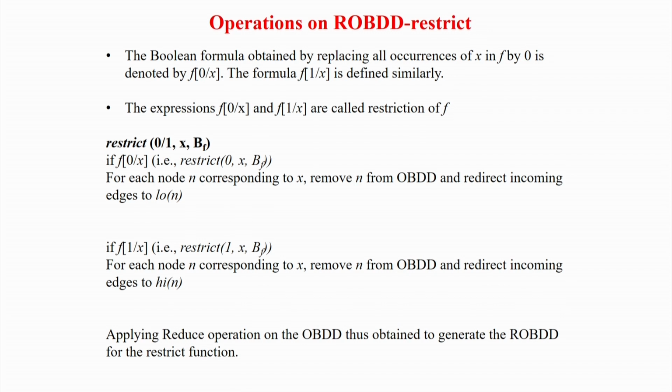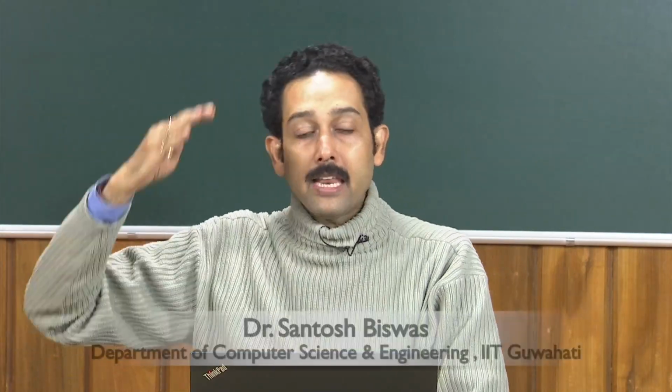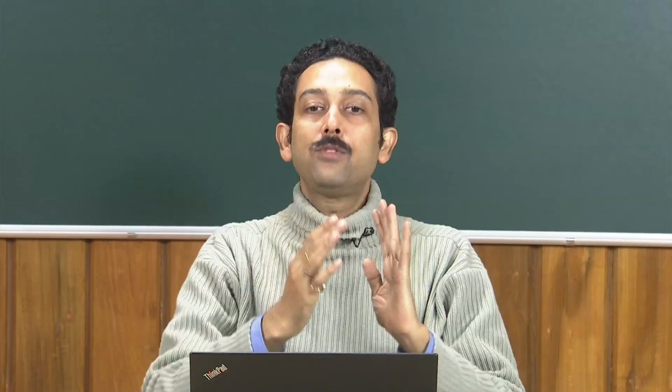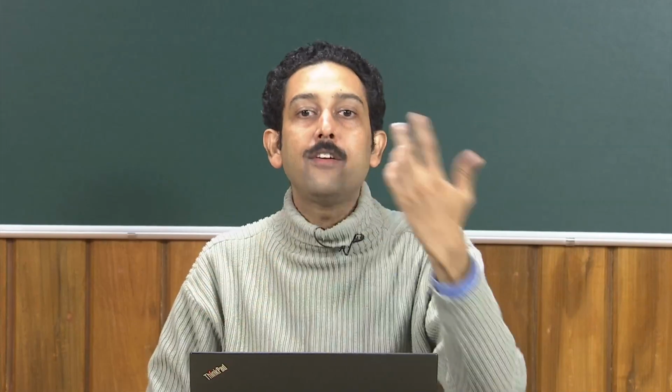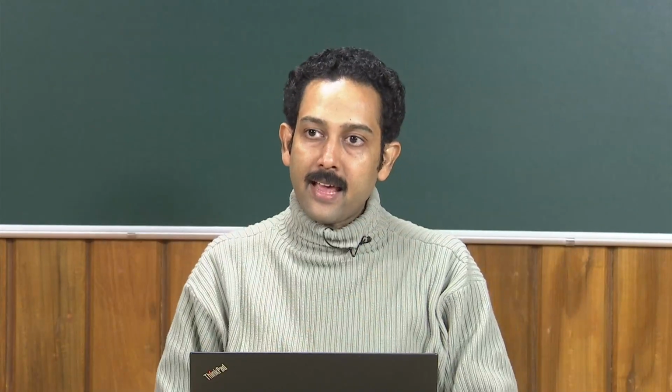You have a very big circuit, take a gate, take the inputs, construct the BDD for the output of the gate. Reduce the redundancy there itself. Then you can take another gate in the forward direction and find out the BDD for the next level of gate and keep on doing it. For every gate computation output of BDD, you have to reduce it at that stage only. It is not like you will compute for two or three gates and then reduce at a time. If you do this, the intermediate BDDs will become very large in size and your whole idea will be lost.